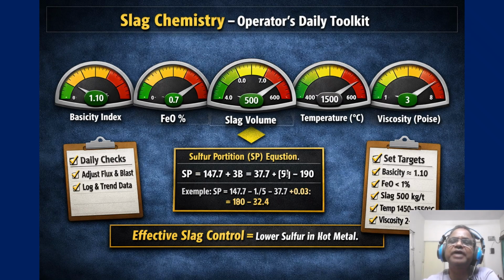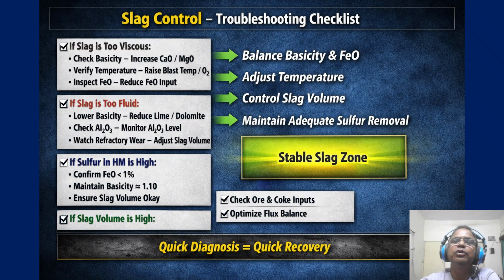Because potassium cycles, it reduces to gas in the lower furnace and then condenses on the cooler body. If the slag is too basic, it traps less alkali. So we have a conflict. High basicity gives low sulfur, lower basicity gives low alkali buildup. So you cannot maximize both at the same time. So what to do? We don't just pick one basicity, we combine basicity and slag volume.